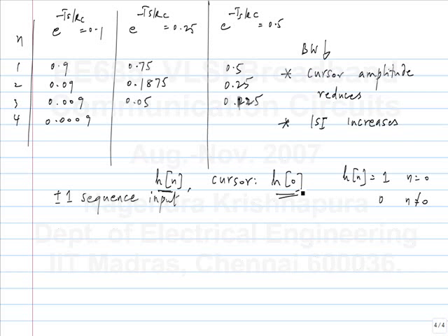In general, the response is h. So it's the convolution of h with the input sequence. So what you receive naturally is h of n convolved with x of n. What is the largest positive output that you can get from this? Sum of all the h. Yeah, so the absolute value, because some elements of h of n can be positive, some can be negative. But the highest you receive is when the ones that are positive are weighted with +1, the ones that are negative are weighted with -1. So this is the largest thing that you receive.